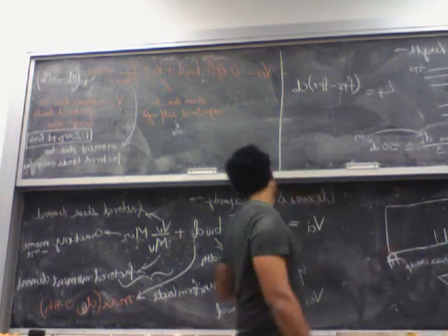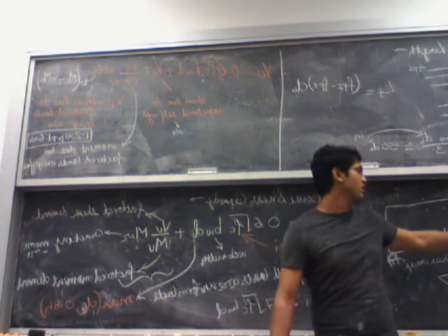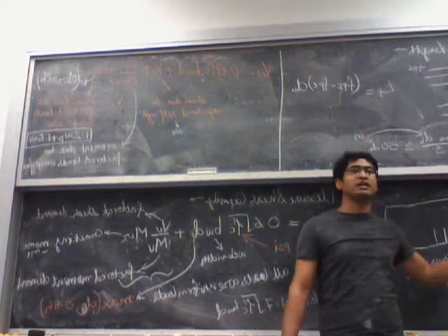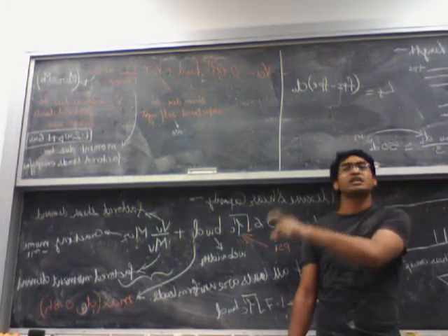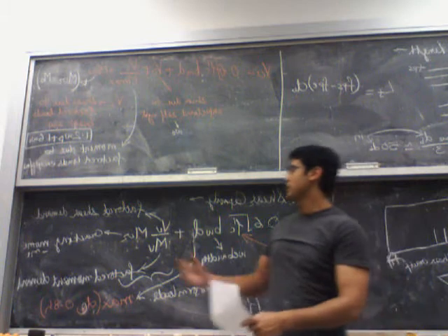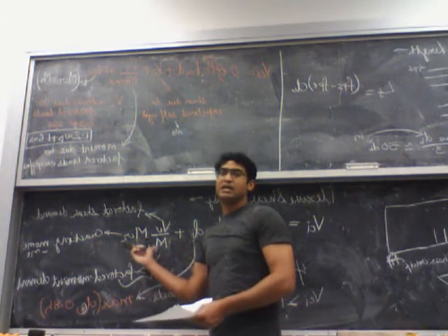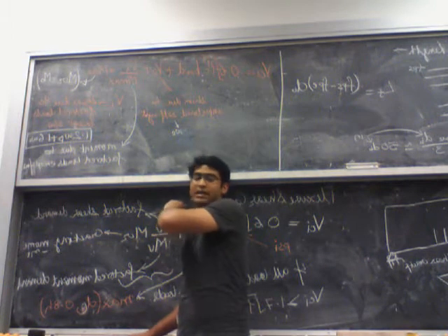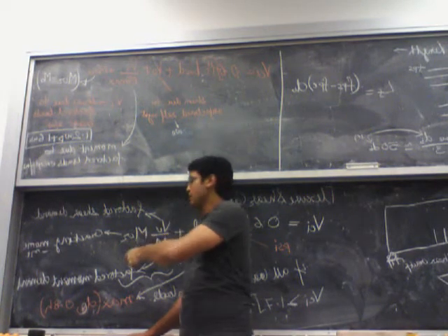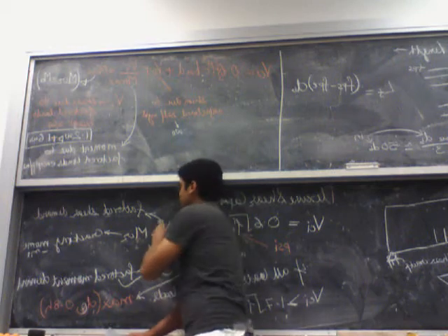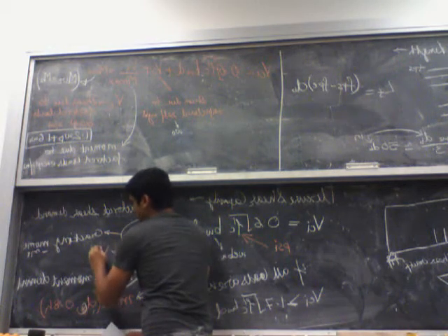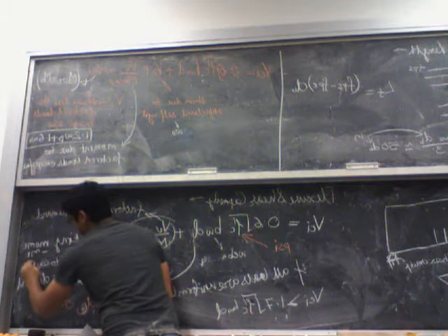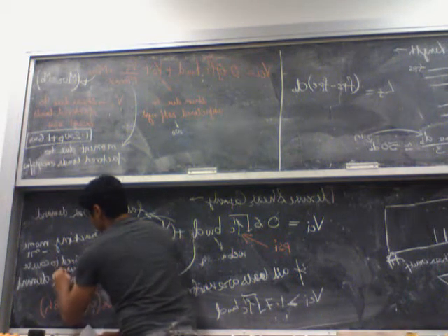What this second term is actually the shear required to cause this first flexure crack. But there is no direct way to relate the flexure crack with the shear capacity. So you take the cracking moment, divided by the corresponding moment applied due to all the loads, which is the self-weight, the dead load and the live load, and you multiply it by the corresponding shear. So what this term is approximating is the shear required to cause flexure crack.